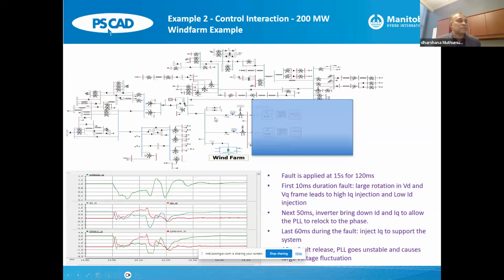Then this is another example from Australia, relatively low voltage 66 kV system over here, relatively weak. There were a number of existing wind and solar in the area, and the study was to connect a new wind farm, right? And we observed a number of issues, right? Voltage recovery, oscillations, and so on. And specific control tunings had to be done in order to overcome the issues and to make this connection possible. So these type of issues again cannot be studied in RMS.